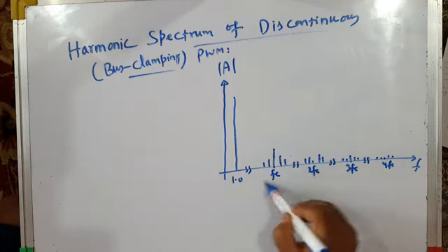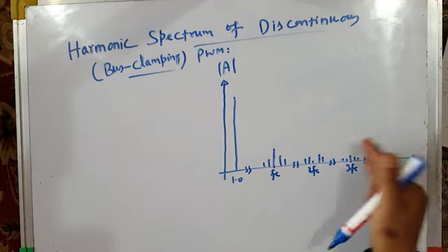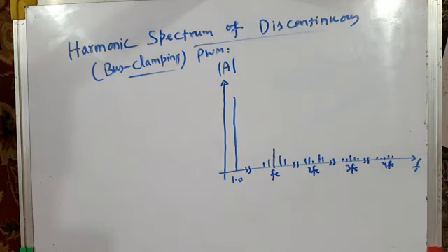So therefore, first sideband and second sideband, we will consider only these, because it is these 2 harmonic frequency components which result in some small flow of harmonic current. And other higher order harmonics will almost produce 0 harmonic current. So we should consider only first sideband and second sideband as far as harmonic voltages are concerned.